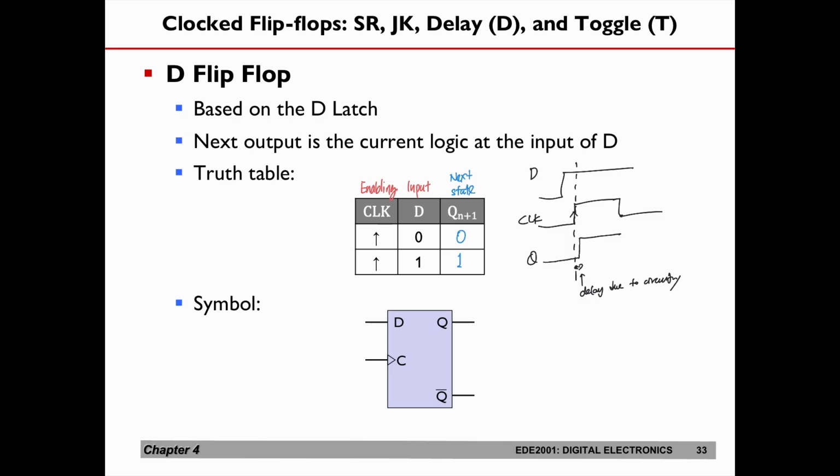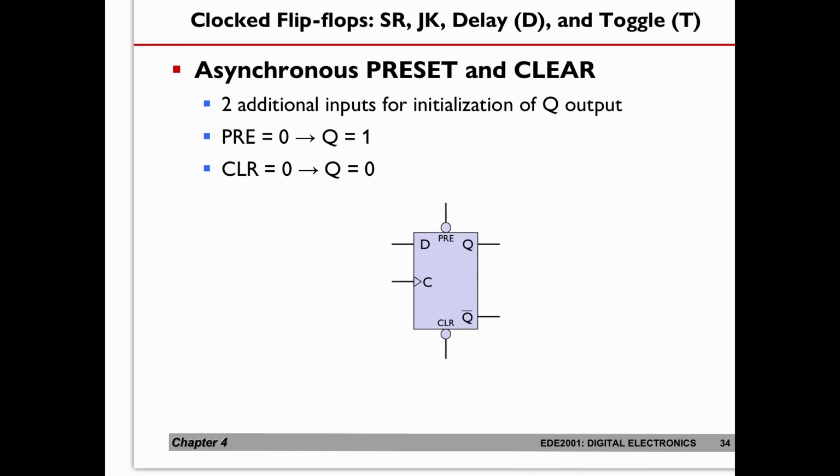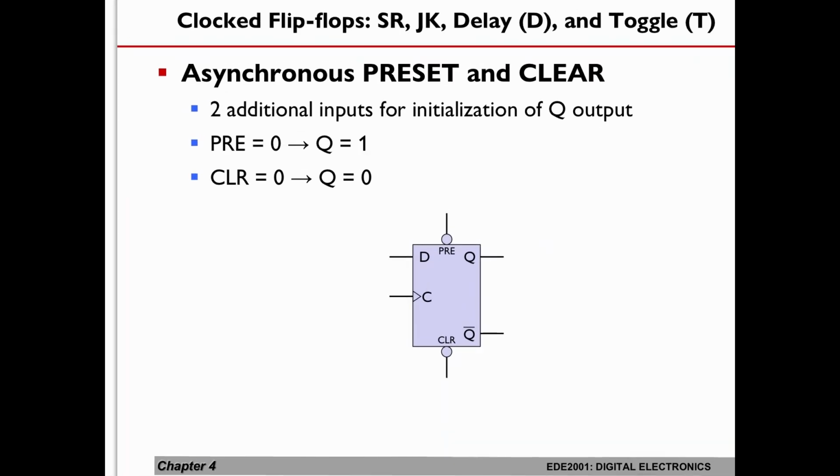Okay, so let's move on to the other features of flip-flops. For flip-flops, we also have preset and clear, meaning that I can preset or clear a flip-flop. Preset means that I'm going to set the output Q to be a 1.